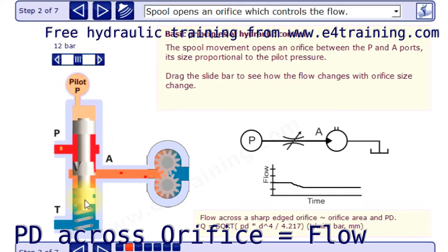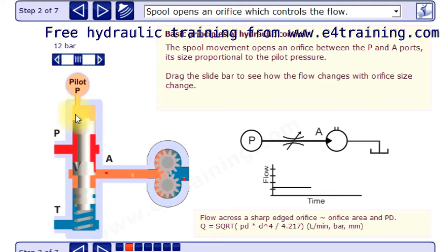Now, the important thing with hydraulic equipment design is the quality of the spool. It's very difficult to make a spool. Clearances between the spool and the bore can be around 6 to 10 microns. When you consider the length of a spool, you have to keep the straightness, the roundness, and the concentricity. It's very, very difficult, very specialist manufacturing to produce hydraulic equipment, and don't try it at home. So this is the main thing.